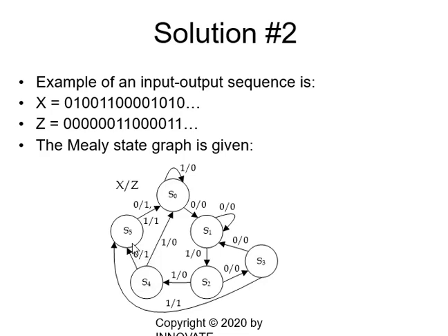From S5, if I receive a 0 or 1, I will go to S0 to reset the network, and the output will be 1. The same thing, if I receive the pattern 0, 1, 0, 1, the output will be 1, and I go to S5. Okay, so here 0, 1, then I receive the 0, so I open a new state, which is S3, to remember the 0.